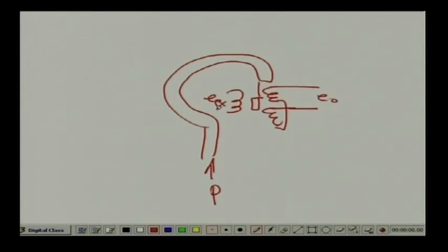If the pressure increases, as you know, this tip will try to move out, so the position of the core will change from the null position, and I will get an output voltage. Even though I said previously that in the case of the Bourdon gauge it is very difficult to get an electrical output, here you can see I can get the electrical output by using an LVDT. So, these are several applications of the LVDT, even though it is basically used for the measurement of displacement.